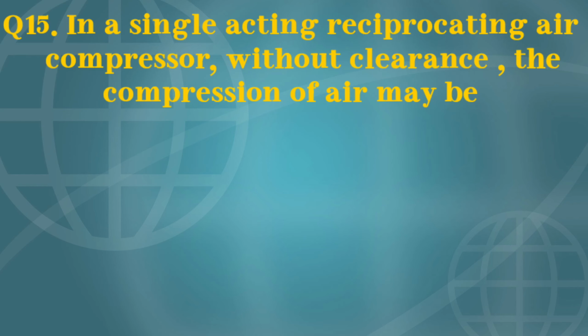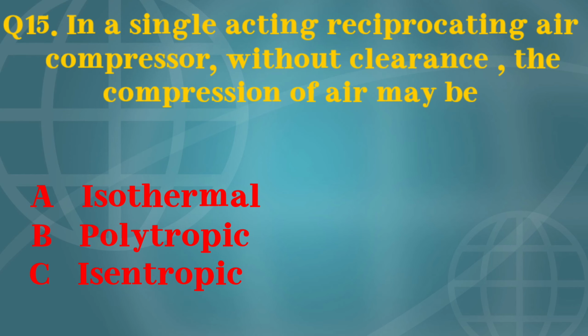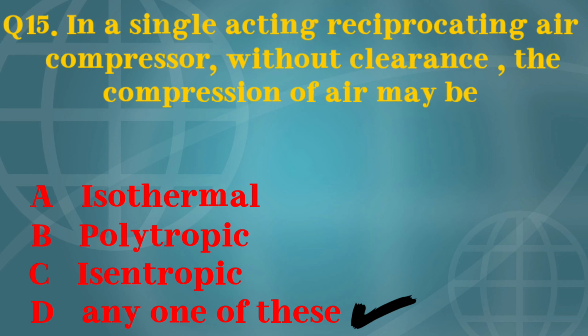Your question is, in a single acting reciprocating air compressor without any clearance, the compression of the air may be. Your options are isothermal, polytropic, isentropic, any one of these. Your answer is any one of these.